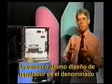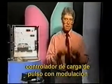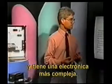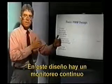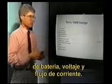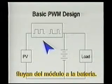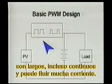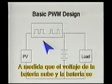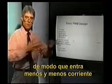A final or third type of regulator design is called a pulse width modulation type of charge controller. This involves more complex electronics. What's going on in this design is more of a continuous monitoring of battery voltage and current flow. Variable frequency pulses are allowed to flow from the module into the battery. When the battery is at a low state of charge, the pulses are quite long, perhaps even continuous. Lots of current can flow. As the battery voltage rises and the battery gets more full, the pulses become narrow and the delay between them becomes longer. So less and less current flows in over a period of time.